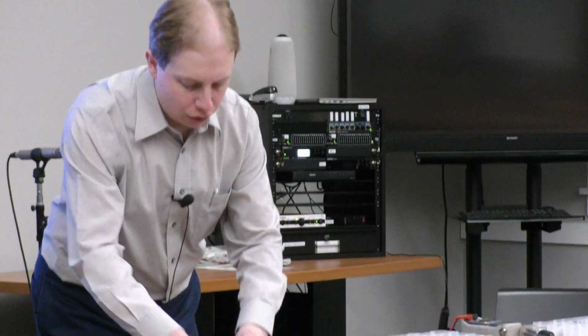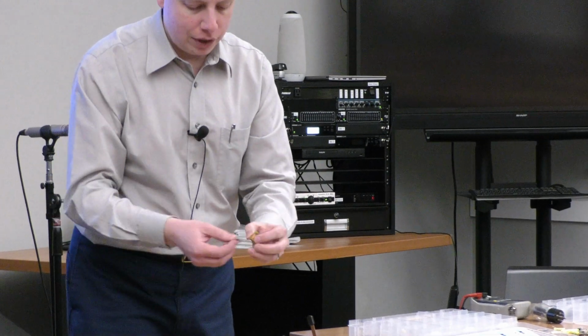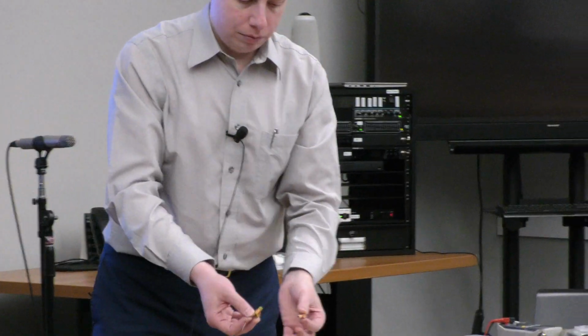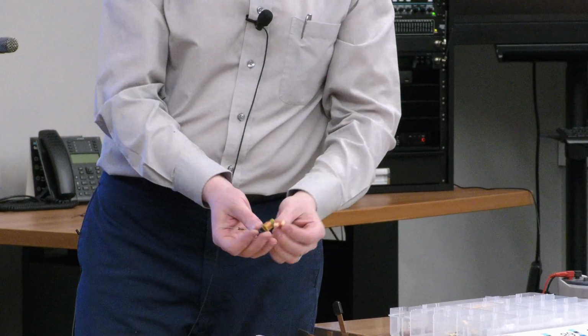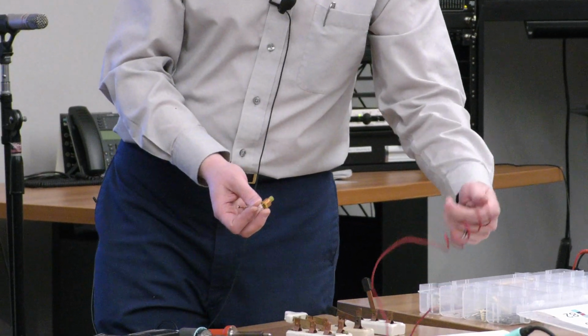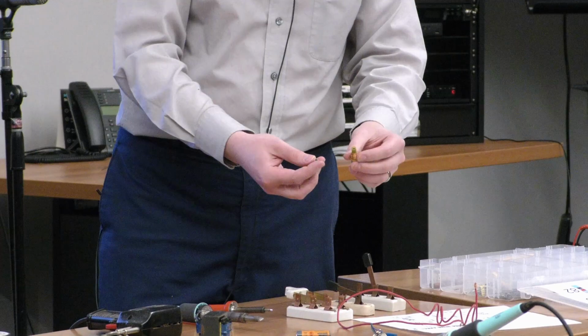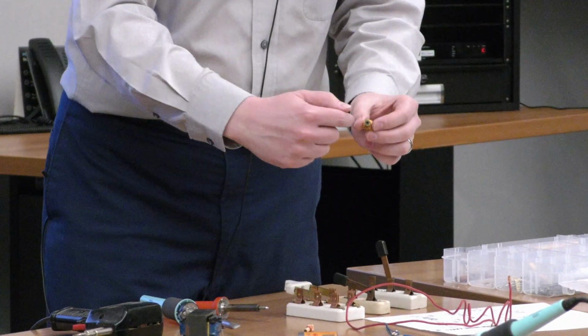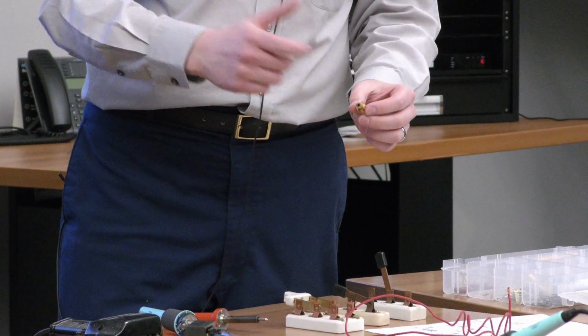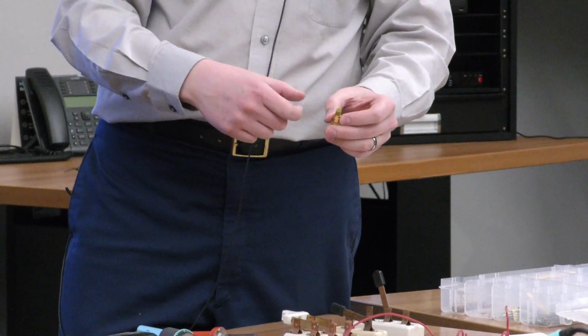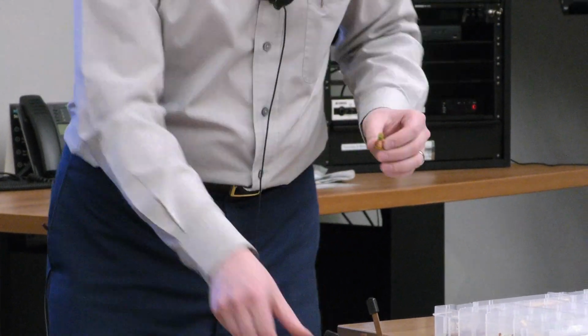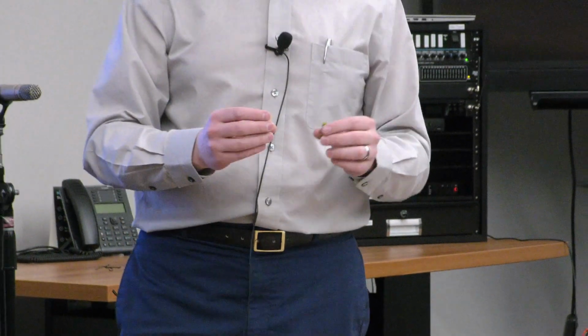I kind of skipped over what inductors look like. I talked about it a little bit, but these are all inductors that I just found in my junk box. Like I said, a coil of wire like this can be an inductor. These two here are actually variable inductors. There's a little ferrite core inside, and you can adjust that core up and down, and that slightly varies the properties of this inductor. So if you're using this in a tuned circuit, you can get that circuit peaked right to the frequency that you want it to oscillate at.